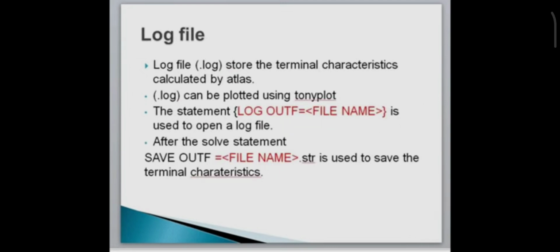The log file stores the terminal characteristics calculated by Atlas. These are currents and voltages at electrodes in DC simulation. In transient simulation, the time is stored. In AC simulation, the small signal frequency, the conductance and capacitance are saved. The log file can be plotted using Tonyplot.